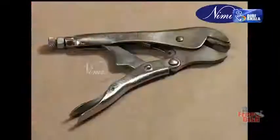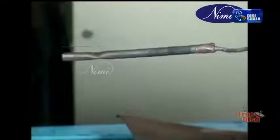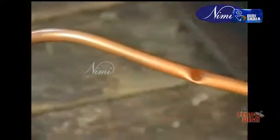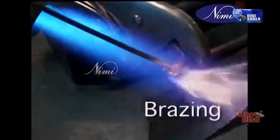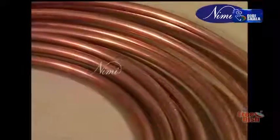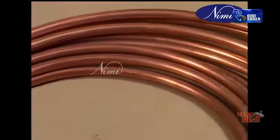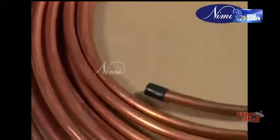Pinching. A pinch-off tool is used whenever it is necessary to seal off copper tubing so that no pressure can pass from one side of the pinch to the other. When isolation of parts of the refrigeration system is required, it is necessary to use pinching. Brazing. The end of the tubing after pinching is to be brazed. Mostly soft copper pipe tubes are used for piping purposes. We can make a joint in 2 ways: mechanical joints and brazed joints.